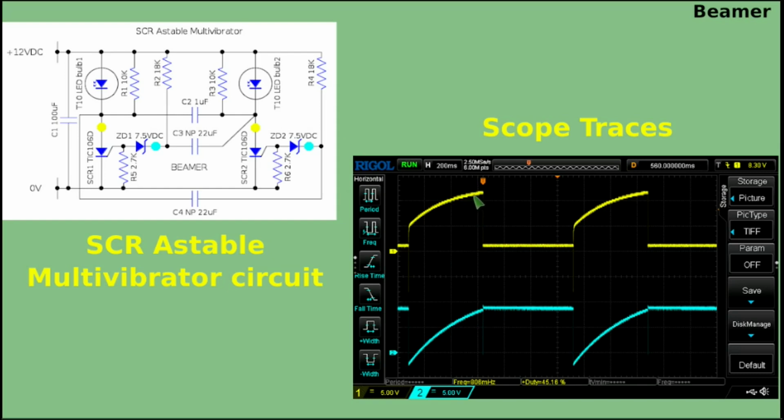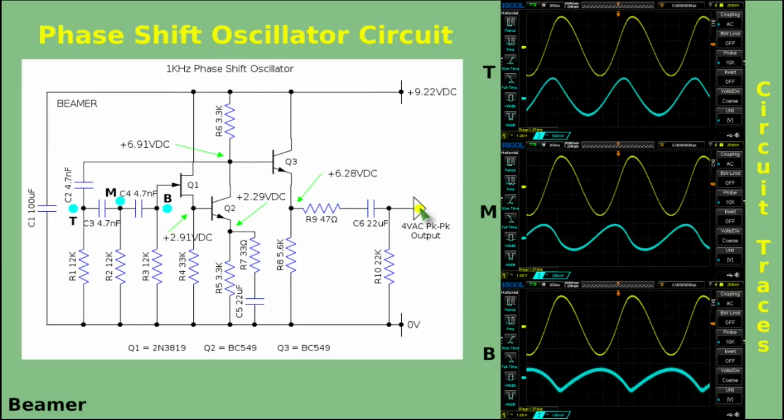And if you look at the anode here, you can see superimposed on the anode the reflective charging that's going on here. And when it reaches this point here, the Zener diode turns on. You can see it's a very clean turning on. It runs for a duration that the other SCR is going through its timing up period. When the other SCR reaches its threshold gate voltage and turns on, I don't know whether you can see this, I can just about see this, but there is here a very sharp, very faint spike, and it represents about 3 divisions, so that's about 50. I would guess it's about 12 volts, and that turns off this SCR, and as you can see, then the cycle repeats itself.